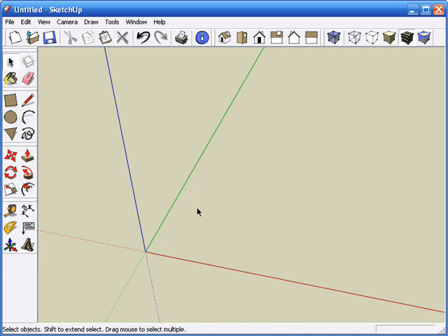And now what we want to do is set this up so we're drawing in the right perspective. This is the first thing you always have to do when you draw anything in SketchUp, is pick the correct perspective to draw in from the start. And you can avoid having to rotate the drawing in odd ways later on. These are the perspective choices right up here.